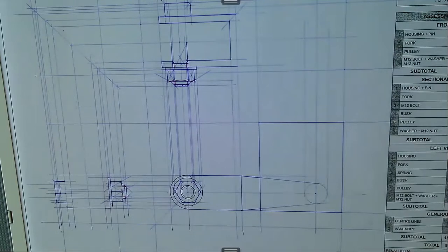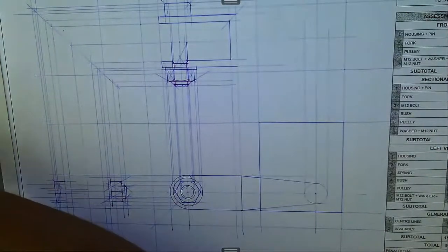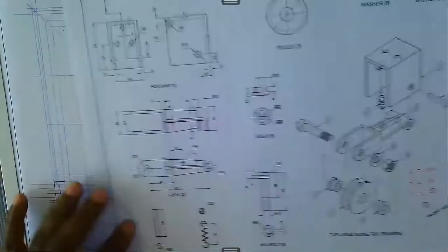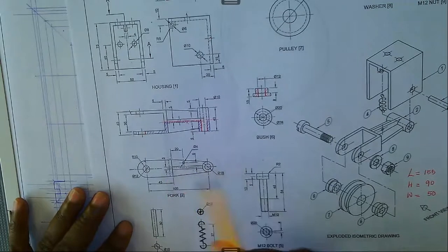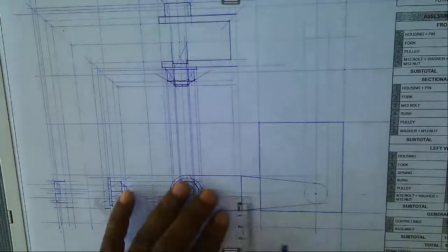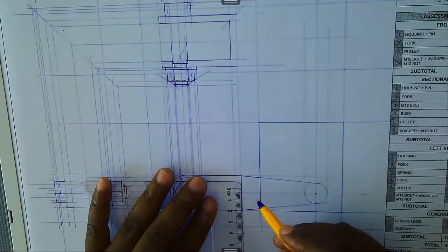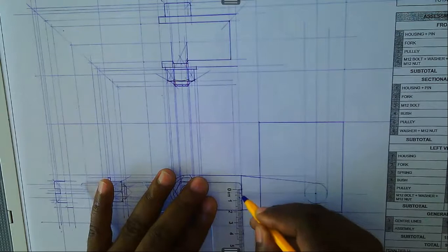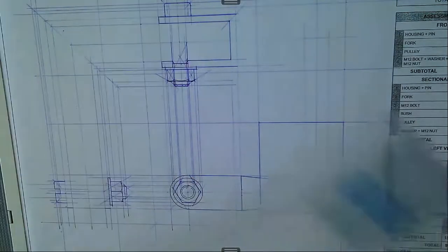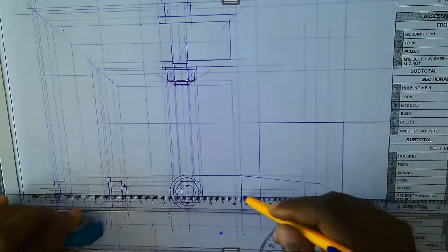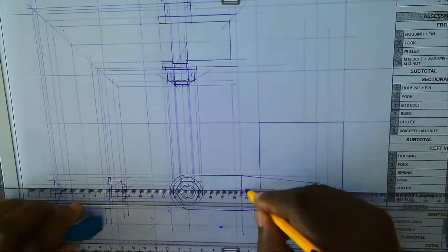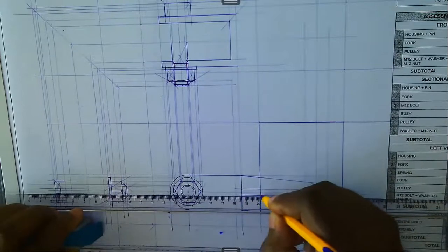There you go. Right. If we are looking from the right, there is also this detail, which is the web. Right. We are told that it's from here to there. Right. It's 5 millimeters. So either side, let's measure 2.5, 2.5. We can just draw it like that. But what is required is this from here to there, from here to there.